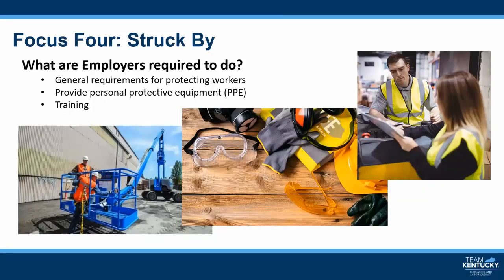The use of unsafe or damaged hand tools is not permitted, such as sprung jaws on wrenches, mushroom heads, or splinters or cracks in wooden handles. Employers must ensure that saws are equipped with guards and have a constant pressure switch that will shut off the power when the pressure is released. They must ensure that safety guards are on all abrasive wheel, bench, and stand grinders, and ensure that only trained workers are allowed to operate powder-actuated tools.